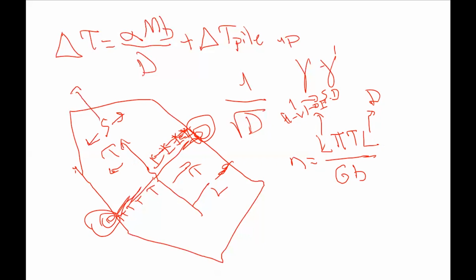And this is the Frank-Read source, which generates the dislocations. And they encounter a lattice friction stress. They need to overcome the Peierls stress. This is tau zero. This is the lattice resistance in order to move these dislocations.